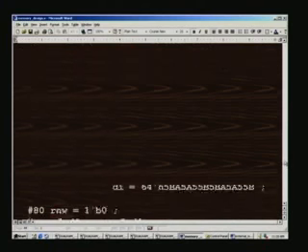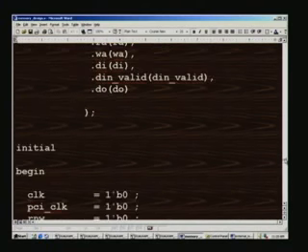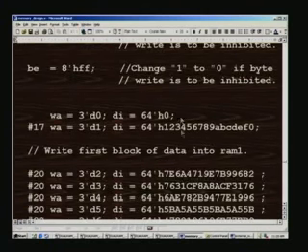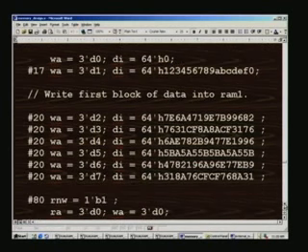First let us go to the very first block we have written. So this is the first block we have written, 0 0. Now remember, while writing we are writing in this fashion, row wise, that is horizontally, while reading we should read vertically. For example, this is the first byte 0 0, then 1 2 7E and so on it should go, and the next must be 0 0 3 4 and so on. So that is how we had to read, right.